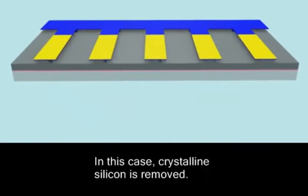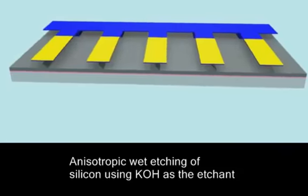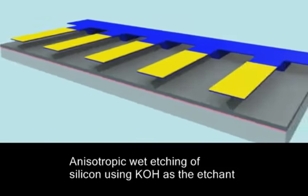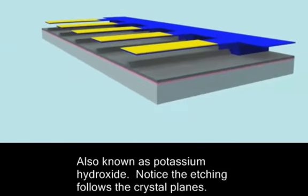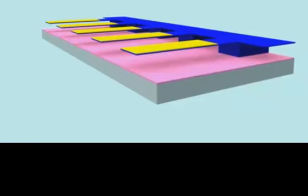Now we can etch crystalline silicon using potassium hydroxide, also known as KOH, and that will actually etch along the crystal planes. That's why you see the triangular formations underneath the masked areas. That is representing the 111 plane, which doesn't etch as fast as the 100 plane.